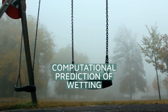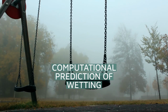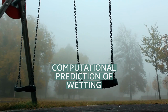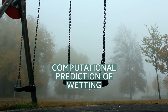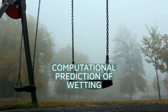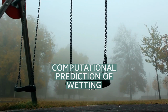Computational prediction of wetting. For many surface-adsorbate configurations, surface energy data and experimental observations are unavailable. As wetting interactions are of great importance in various applications, it is often desired to predict and compare the wetting behavior of various material surfaces with particular crystallographic orientations with relation to water or other adsorbates. This can be done from an atomistic perspective with tools including molecular dynamics and density functional theory.